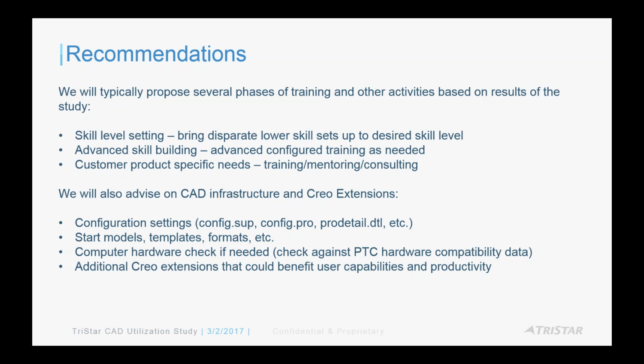We will also advise on CAD infrastructure and Creo extensions. What configuration settings you have in your config.sup, your config.pro, your pro detail, etc. Start models, templates, formats. We also check your computer hardware against the PTC hardware compatibility data. And we'll make recommendations on additional Creo extensions that you could benefit from, capabilities, and productivity.